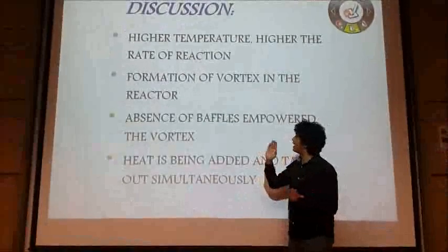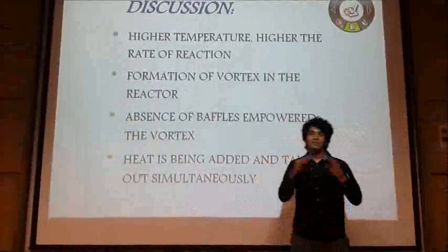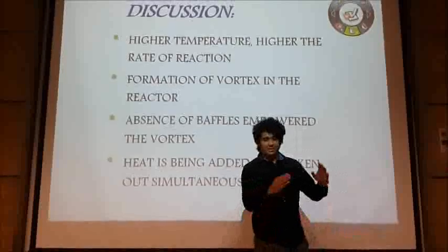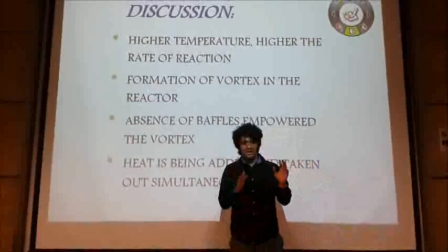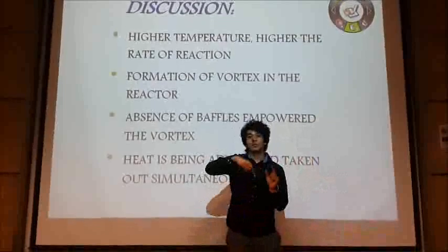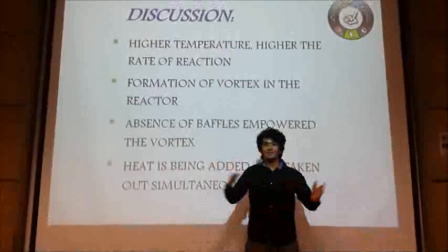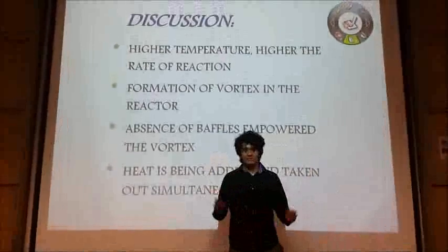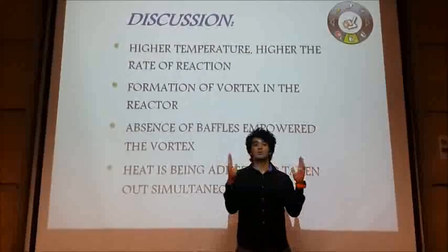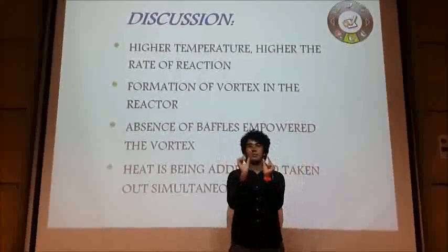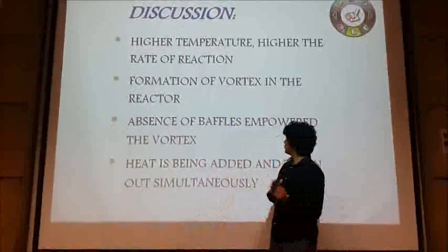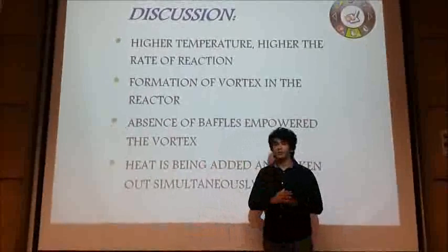Next will be the absence of baffles. The absence of baffles actually empowered the formation of a vortex. The purpose of the baffles is to destroy the whirling motion of the water, in other words, to destroy the vortex. The baffles are just slight structures that make the reactor look smaller on the inside. There can be 2 or 4, depending on how many we need. So yes, the absence of baffles did empower the vortex.